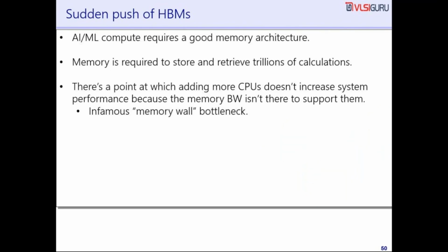Also, because all these DDRs, the GDDRs or even the DDRs, are connected at the periphery of the chip, that also becomes a limiting factor in terms of the bandwidth.